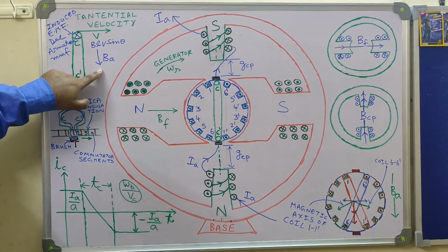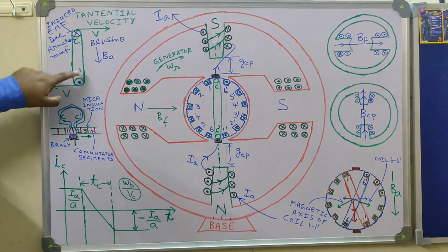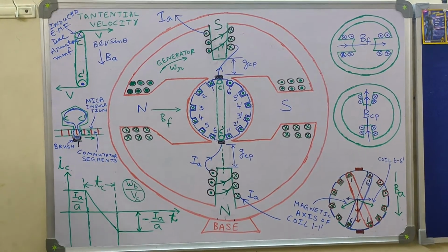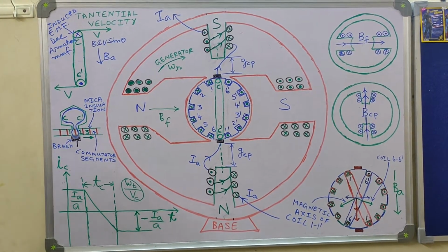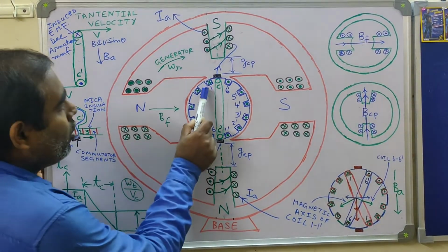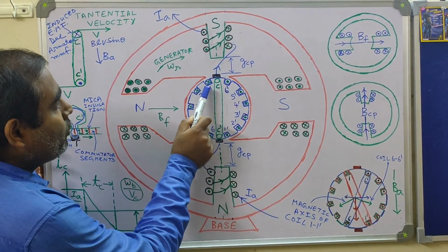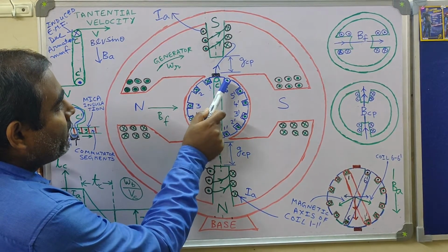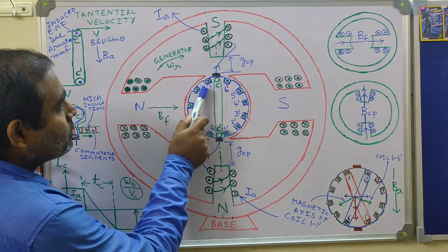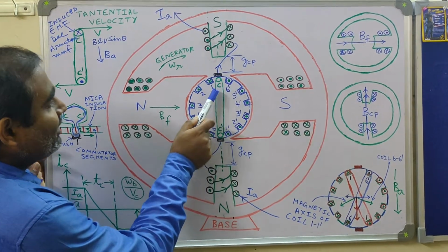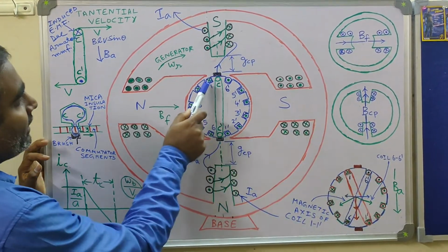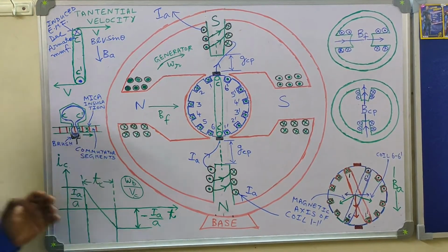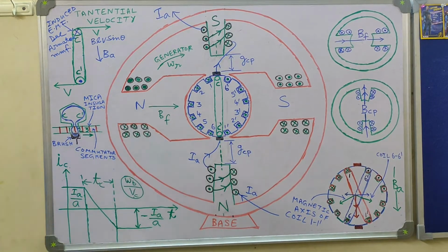So due to this, armature EMF is being induced in the commutated coil, which is giving a hindrance, or obstruction, in the reversal of the coil current. That means it is not allowing the cross to become dot. Rather, it is helping to retain this cross. It is not helping the cross induced EMF to become dot. Rather, the armature flux density BA is helping the coil side 1 to retain the cross, as you can see from this induced EMF. So what has been done?